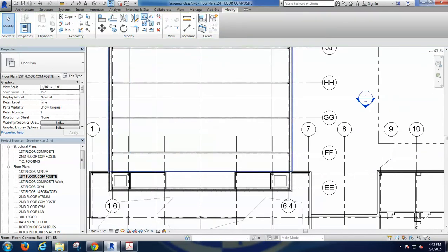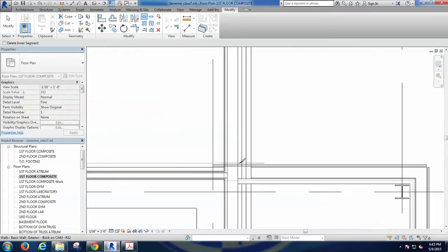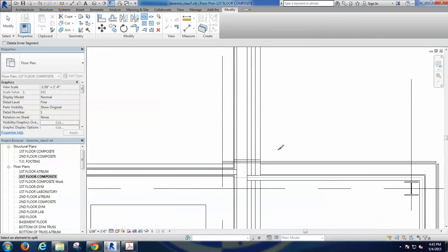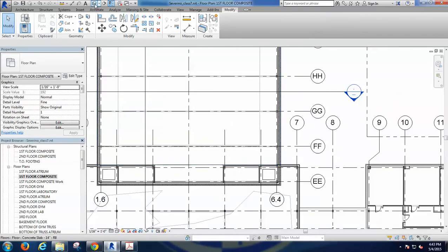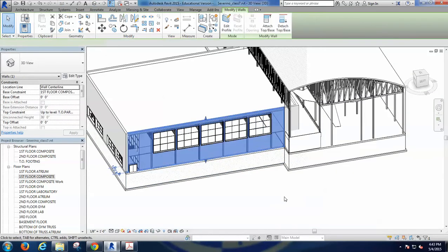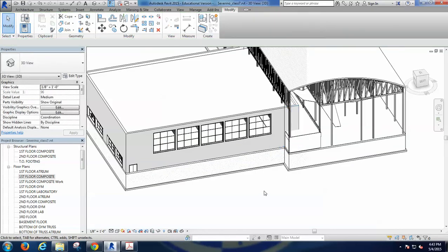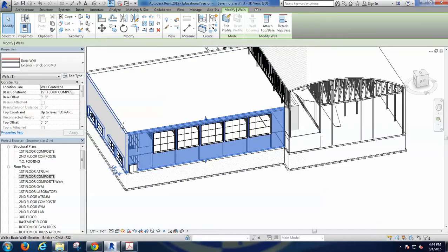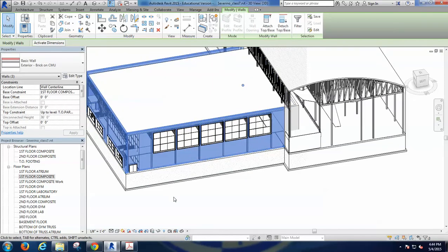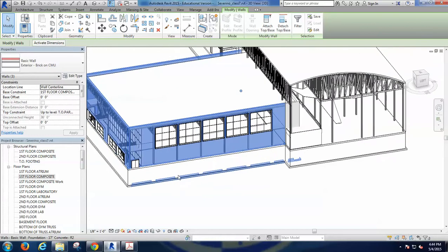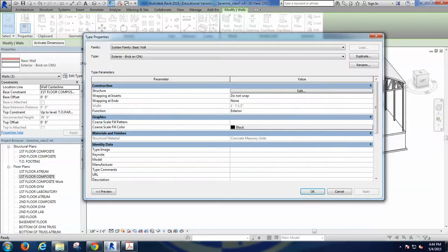Okay, I'm going to split again this other wall here so we don't have any trouble. I'm going to split it just a bit outside of the curtain wall. Again, this becomes one wall separated from this one. Okay, and that will carry on with all the different conditions that have to be met. So now I'm going to select this wall. I'm selecting the three of them because these are going to be duplicated. I don't want to mess with this wall that we placed a long time ago. We never gave it a name, like, this is my wall.